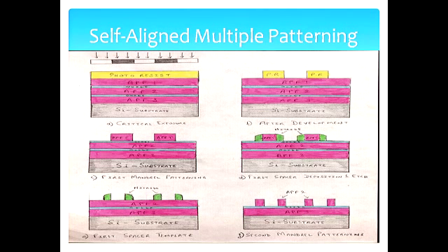Yes. Oh, cool. So on the silicon substrate, you are using another layer, APF, right? Why did you choose that material? Oh, it's a standard patterning material that's used in the industry. I mean, you can use polysilicon, but polysilicon does not give very good edge roughness. This is a good one. Can we use any material? Yes.